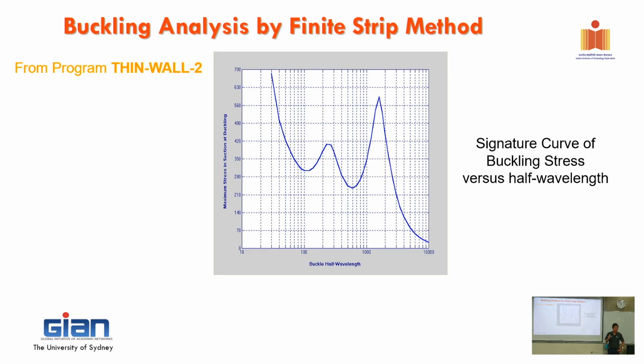And importantly, it gives you straight away the location of the shear center and centroid. You don't have to worry about that, and it gives you Iw, the warping constant. Everything is just one click. You don't have to go to a lengthy equation in the appendix of the standard. That's the other choice, okay? So that is the first thing. They give you the property of the section.